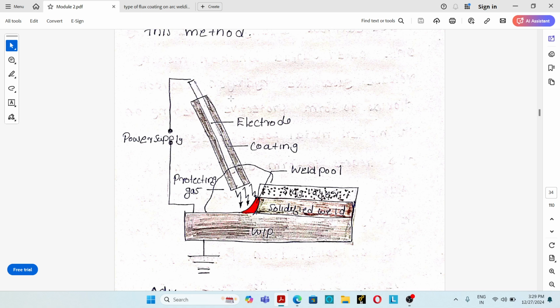During welding, when the electric arc is struck between the end of the electrode and the base metal, the electrode gets melted and material is transferred to the molten weld pool through the electric arc. The flux undergoes a chemical reaction producing hydrogen and carbon dioxide gas that provides a protective cover over the molten weld pool and separates it from the surrounding atmosphere.